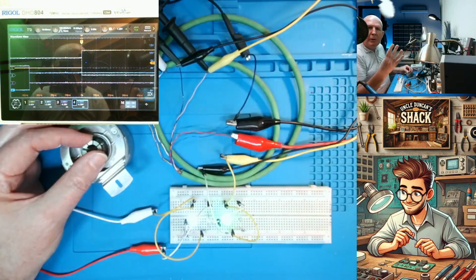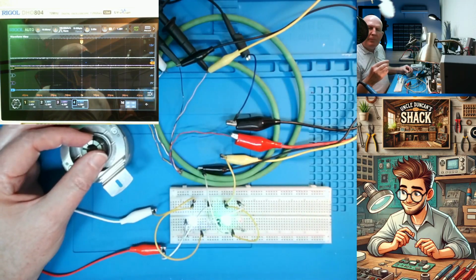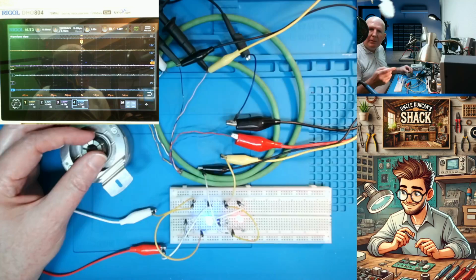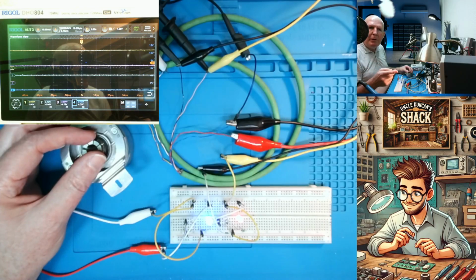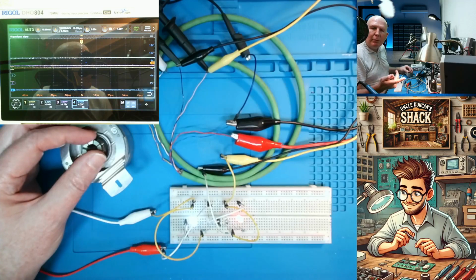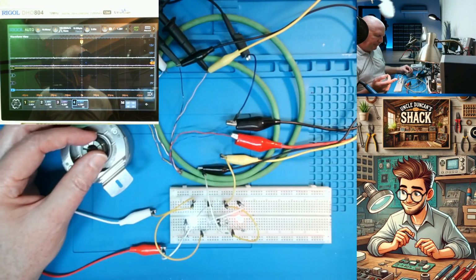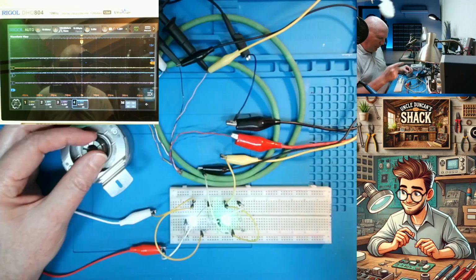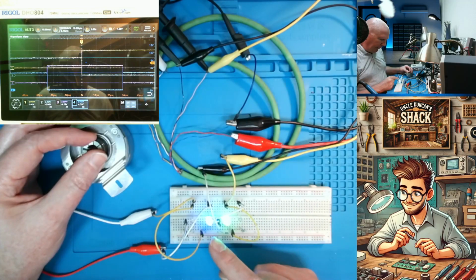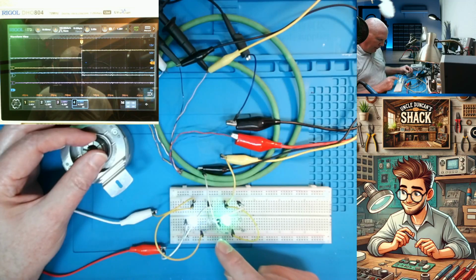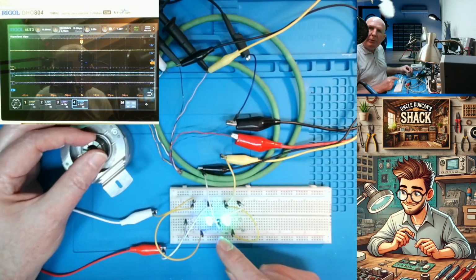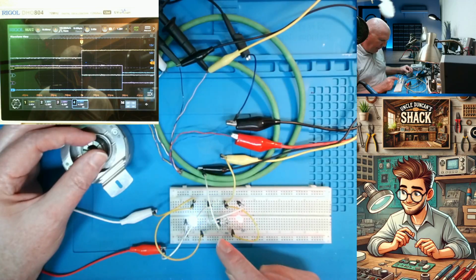So those are the 4 wires that come out of an incremental encoder with RS485 differential signals, alright? An HTL encoder will only have an A and a B, it won't have a complement. The A naught and the B naught is called a complement. Alright? So if you don't have a scope, you can just use LEDs on the output, in this case with some 330 ohm resistors, to see whether your encoder is working. Alright? Like that.